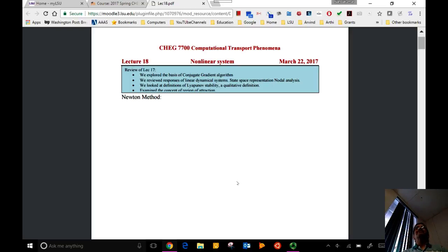Fluent is kind of ahead of that. COMSOL is catching up very rapidly, I think. But you can try the k-epsilon model to begin with. You will learn something. You may find that the k-epsilon model is not doing as good a job, and you will explore why that is, and you can understand and interpret and write that in a report. That's fine.